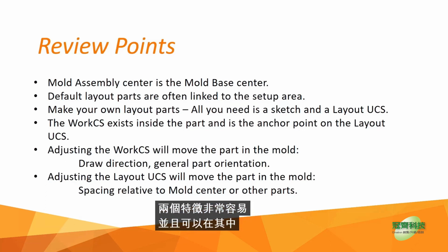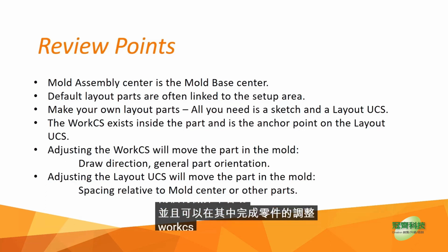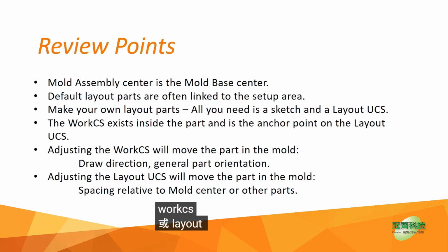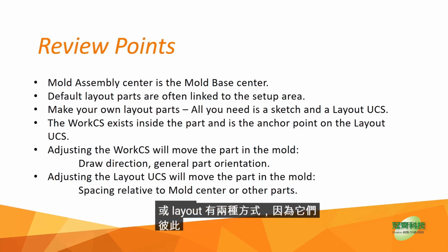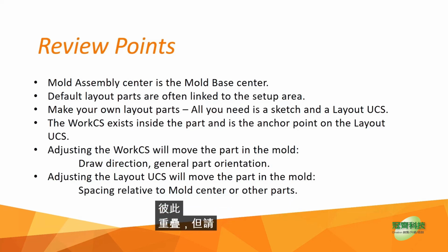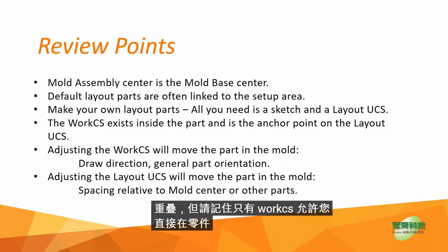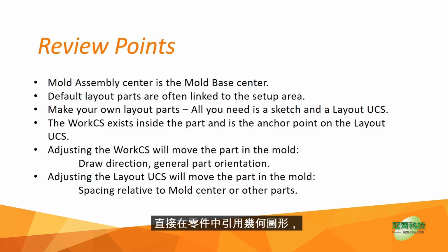And adjustment of the parts can be done in 2 ways, by the WorkCS or the layout, because they sit on top of each other. But remember, only the WorkCS allows you to reference geometry directly in the part. So that's the one that you typically use if you want to change the draw direction of the part.